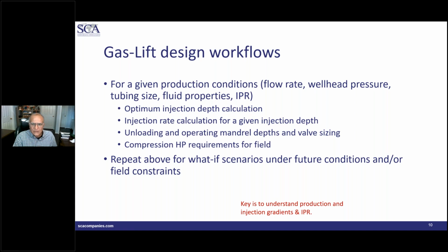Now, it is relatively a smaller exercise when you have to do it for just one set of flow rate, one set of operating conditions, namely wellhead pressure, tubing size, etc. But when you have a situation where you're trying to look over a large number of wells and you're in the greenfield type of development, then you have to conduct this type of exercise for a wide range of scenarios, future conditions, and also you have to keep in mind the field constraints with the time.